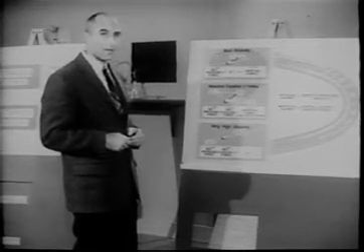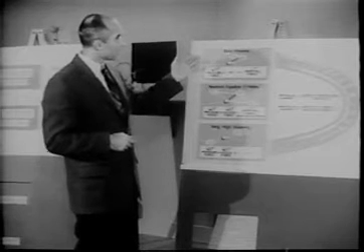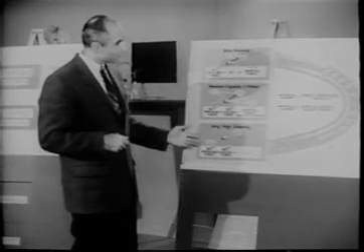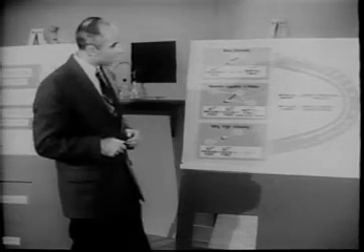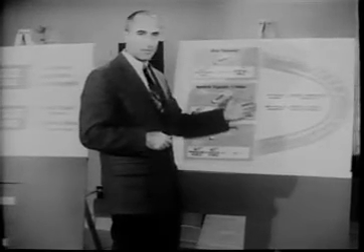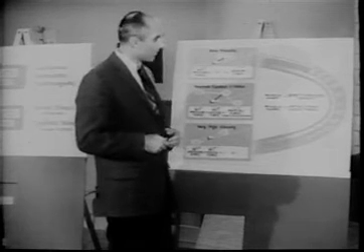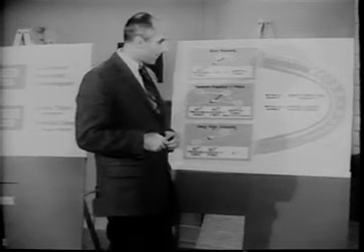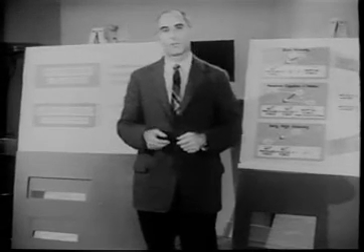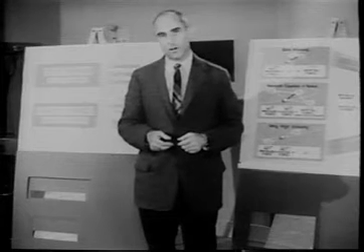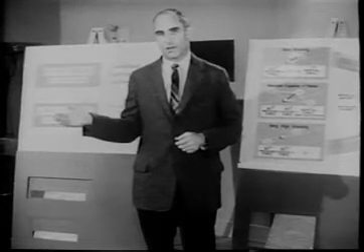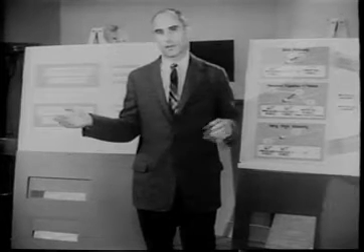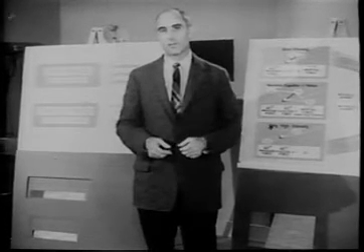Then, by thinking about two extreme cases, fluids of very small viscosity and fluids of very large viscosity, we were led to a most useful idea, the Reynolds number, which allows us to categorize the type of flow in terms of the relative importance of viscosity. Finally, we recognize that the drag on an object, like the forces on a fluid particle, could be divided into two parts: pressure drag and viscous drag. This set of ideas is a powerful tool for interpreting and explaining experimental observations.